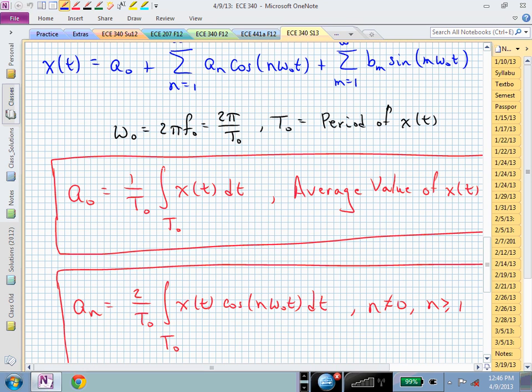So whatever n plus 1 or n plus 7 is floating around, you look at the coefficient that scales cosine of 5 omega naught t. That coefficient will be the amplitude of that fifth harmonic. So don't worry or get too hung up on the n's floating around if they're all over the place. Just find the coefficient associated with the cosine and sine of 5 omega naught t, and that will be your A and B for that fifth harmonic. Does that help answer that question?